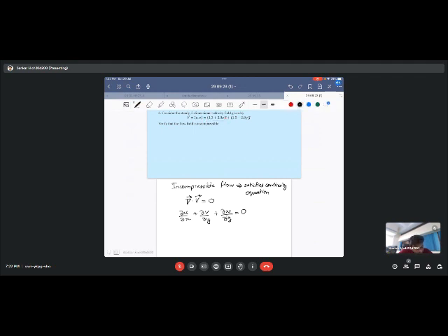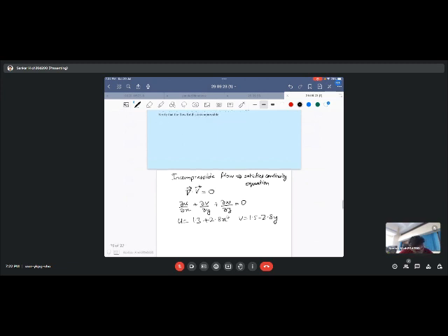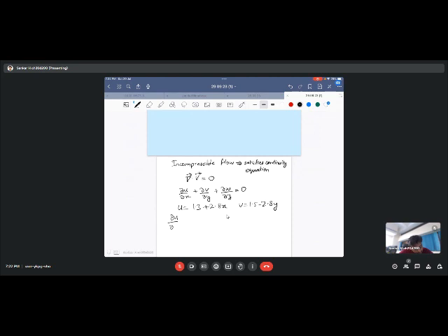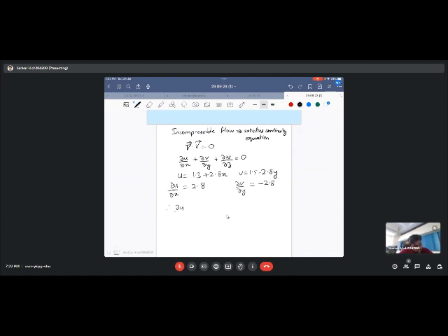Dou by dou x of, okay, let's write it down anyways. You know that u is given by 1.38 plus 2.8x. V is 1.5 minus 2.8y. So here dou u by dou x would be the differential of the term that's shown above, which is 2.8. Similarly, dou v by dou y will be minus 2.8. Therefore, dou u by dou x plus dou v by dou y should be equal to 0.